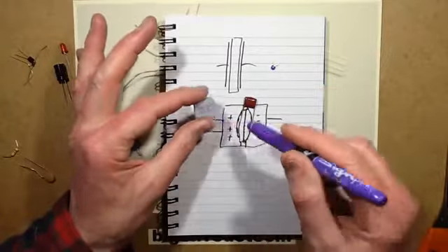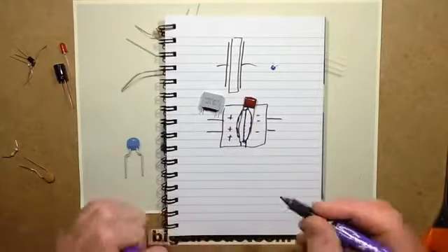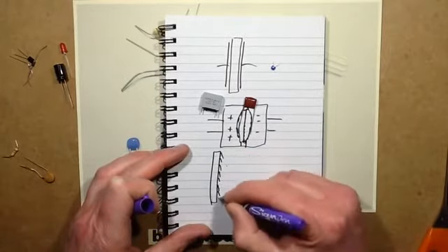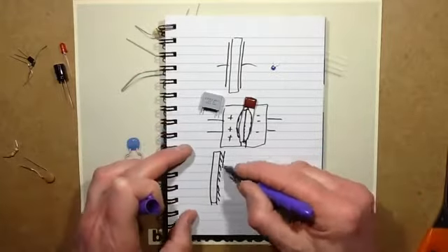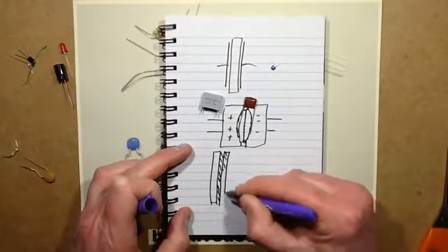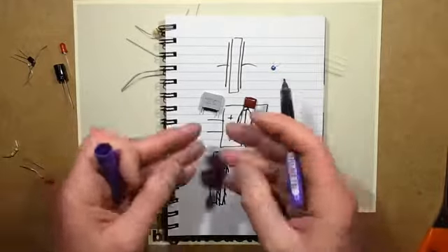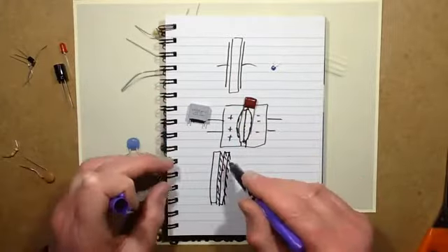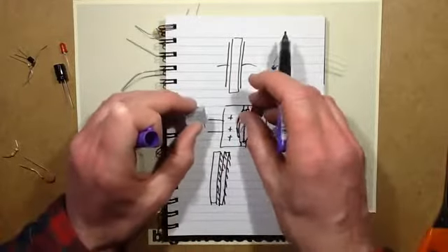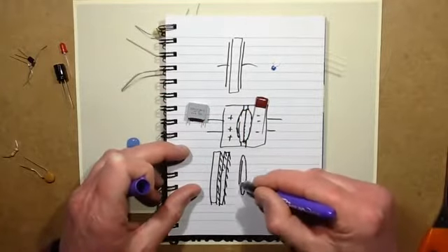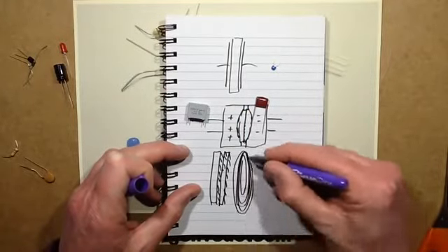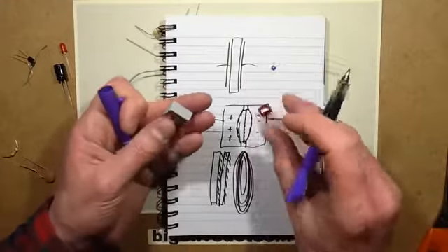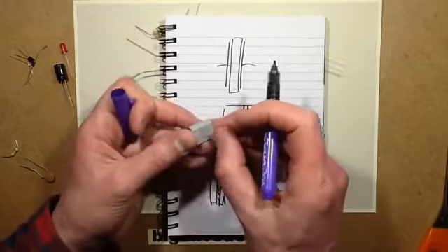And to make this type of capacitor, these are metallized film capacitors, and it's a film that's metallized on one side. They take two strips of it and they basically sandwich them together. The plastic aspect of it is the insulator, and the metallization is the electrode. To fit a lot in a small area, they then actually just spiral. They take a big long strip and they spiral it round into a small area, and that's what creates the sort of larger area. And the thickness of the plastic film itself will determine the voltage rating.